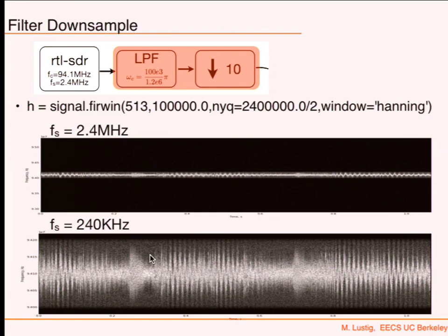And that's fine. Okay? So I could have sampled it by a factor of 6, for example, and it would still not give me aliasing. But the roll-off of the filter would maybe alias a little bit, like I showed you with the SDR. Okay? So all these things, again, you'll see make more sense. So then you're going to do this. Look at the spectrum. It looks FM modulated. That's great. Okay?